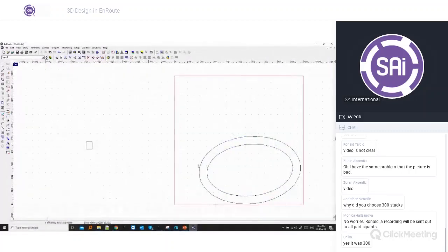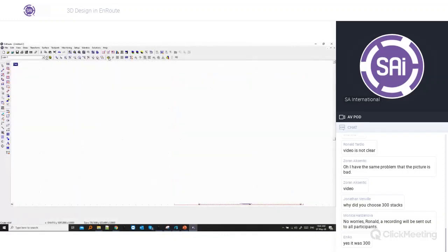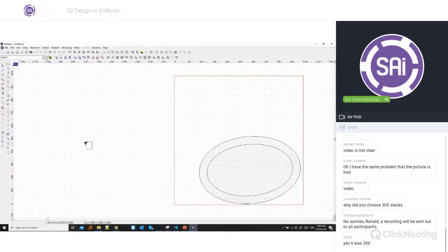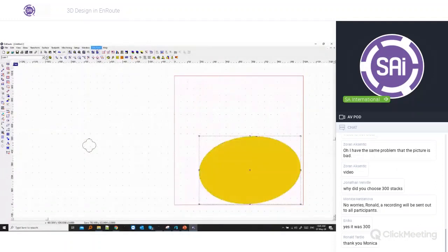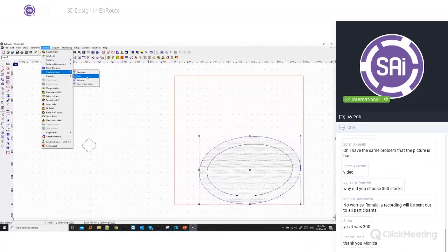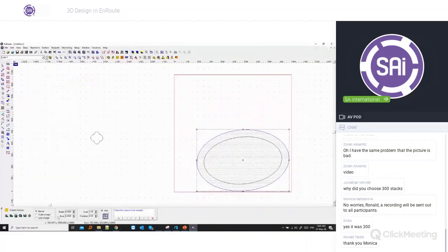We can use this one to create a flat relief, so normal flat relief. And then use our point editing tools to modify this contour to be extruded. Then we're going to modify this relief, so we're going to select it first. Then we'll go to surface, create surface, choose extrusion. We'll select our contour and our path to follow.